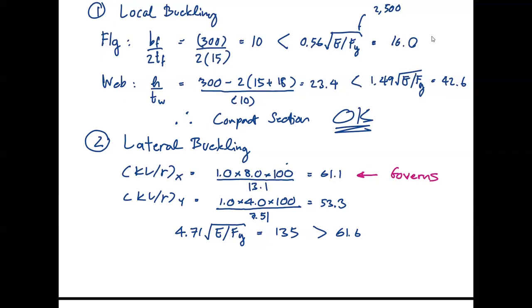What do we have? No buckling? No. Elastic? Yes, it's inelastic buckling. It will buckle. Okay, I appreciate your participation. That means you're not quite getting the hang of it yet. Your column will buckle, your entire column will buckle. The question is how. So we determine this. We know that it is going to buckle inelastically.